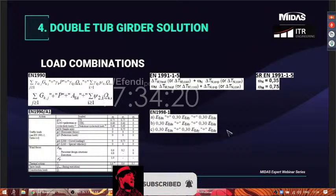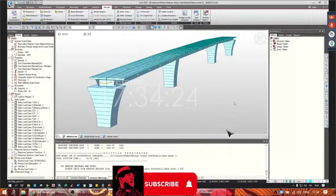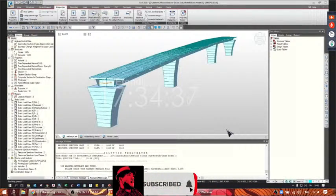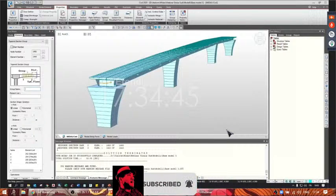Okay, now we go to the MIDAS model. Here is the model. Piers are realized with a line element, with a variable section in both directions. We need to create a table group here, four table groups for each pier, to make the shape in the right way, since we have many elements to manage together.